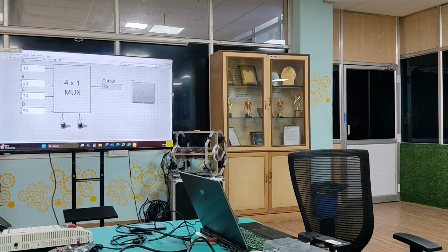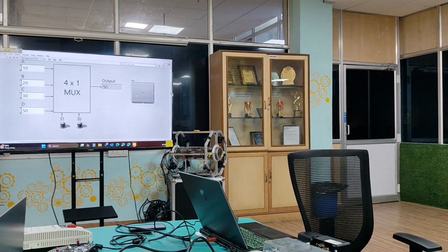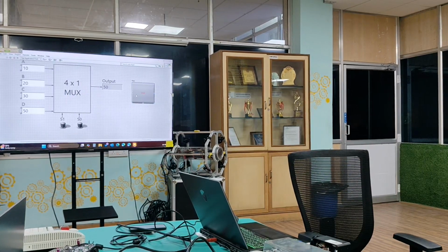You can right click on the red color dot, and you will get the options: stop if true, continue if true. Stop if true means whenever you send the true signal, it will stop. Continue if true means it will keep running as long as you send the true signal, and stops when it gets false. So if I set it as continue if true, clicking the stop button is taken as false. The reverse will work.